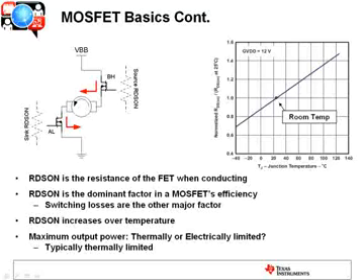Now, another thing you've got to look at when you look at MOSFETs or motor drivers, they're rated in terms of a continuous current and a peak current typically. What you'll find out is many times the maximum continuous current is limited by the thermal performance of the device. Meaning, electrically, so the supply voltage and the load that it's driving, the amount of current you're outputting, electrically the motor driver can easily handle that. But as that current is flowing through those FETs, that RDS(on) is a little resistor, it's heating up. And the die temperature is going to get excessive, and an over temperature event is going to occur.